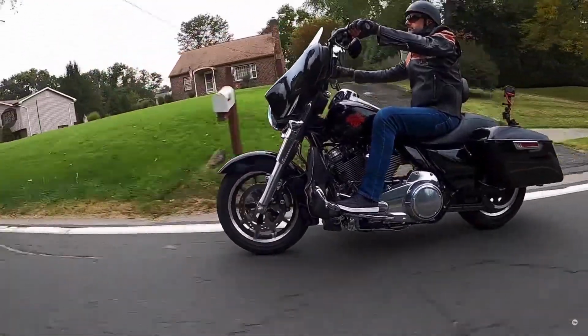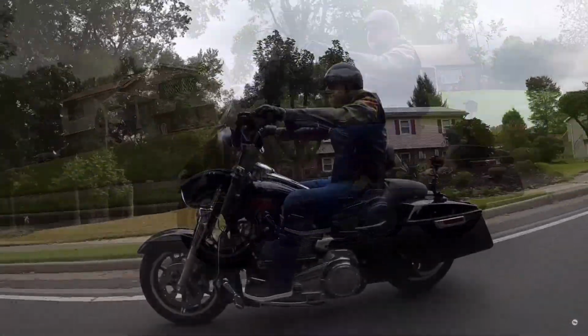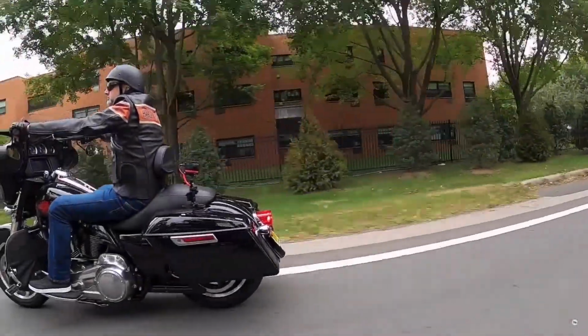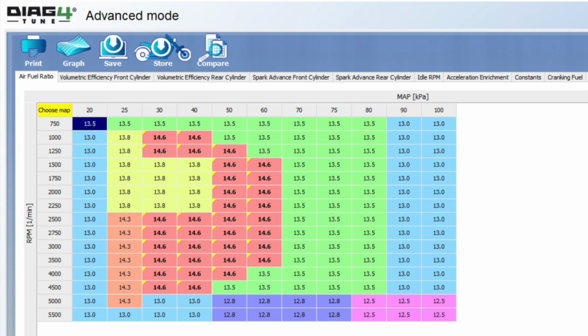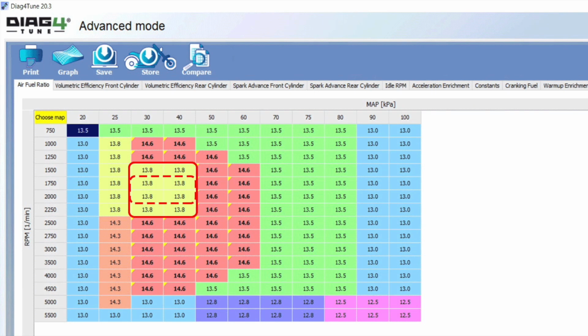After testing, it was found that the cause is an unstable oxygen control loop in the controller unit's program. The issue is thus not a mechanical malfunction, but a system error. The adjustment to the AFR map that suppresses this behavior is indicated here. The setting deactivates the oxygen control loop in the unstable area, and an enriched fuel mixture completely eliminates the negative behavior.